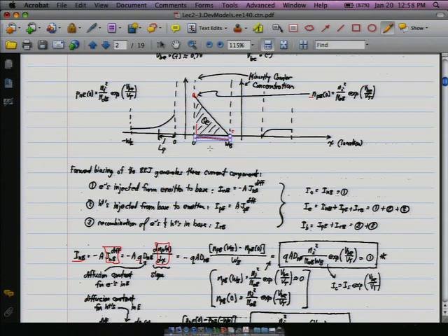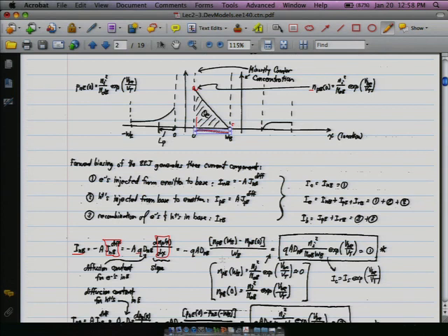And so what this comes out to is you can notice here that there doesn't seem to be much carrier concentration. So that's approximately 0. And so it's this other factor that's going to end up dominating, and that's what comes out over here in the math. So we can basically expand this whole thing to this form, and then this over here is the part that we now kind of ignore, or I shouldn't say we ignore it, but we express it in the future just as IS.